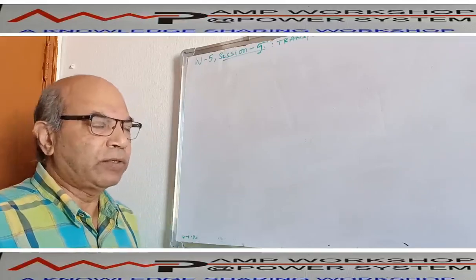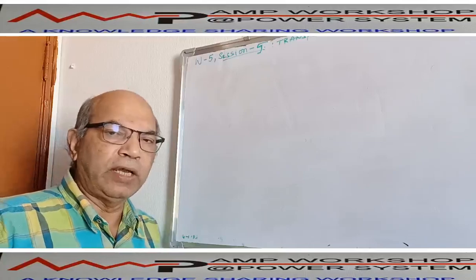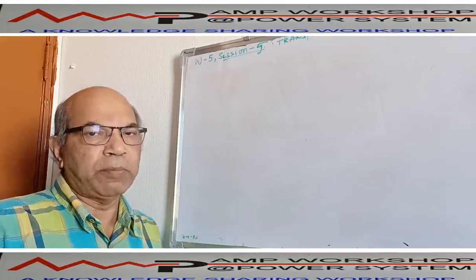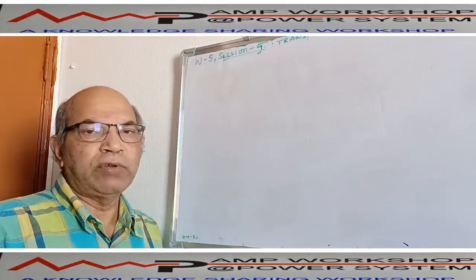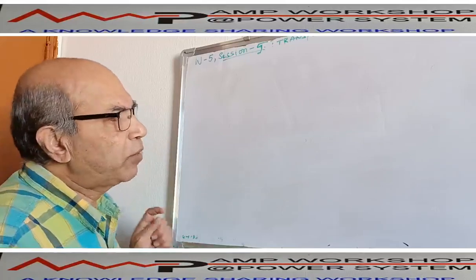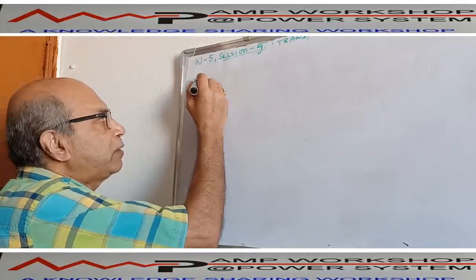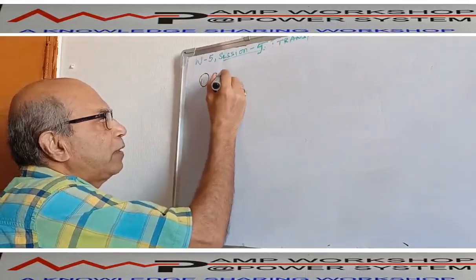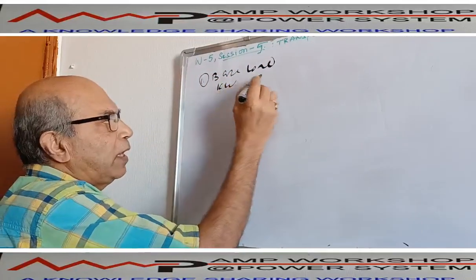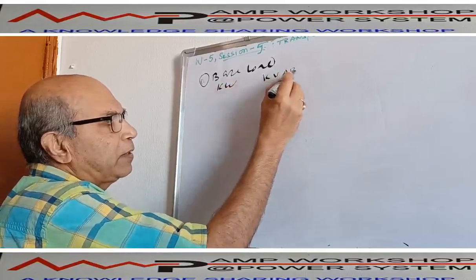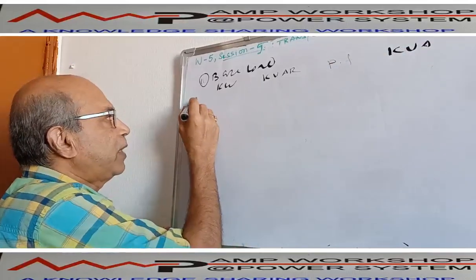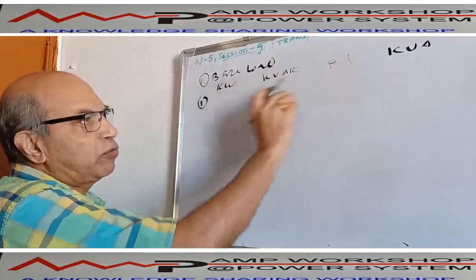Let us consider an installation. I will first use a common, general approach. Once the general approach is over, we will use a specific numerical example to clarify it. For the general approach, we have 2 types of load. One is the base load or continuous load. This base load has 3 parts: a kilowatt part, a kVAR part, and a power factor. And we can calculate kVA from there.